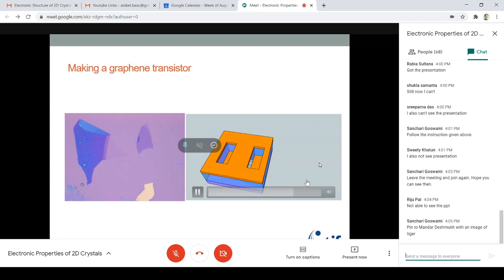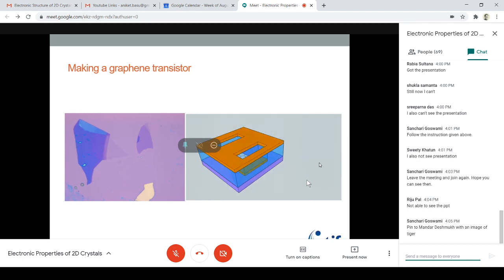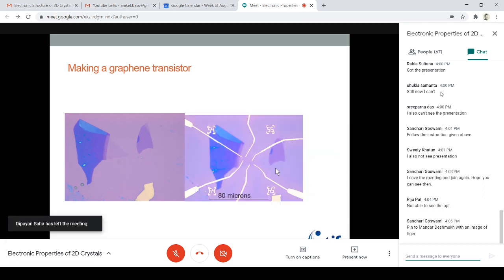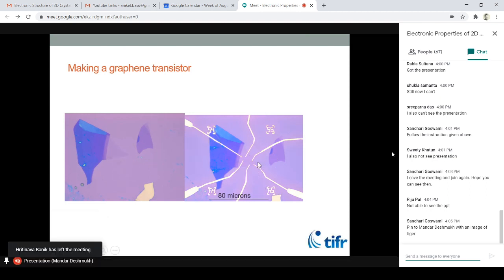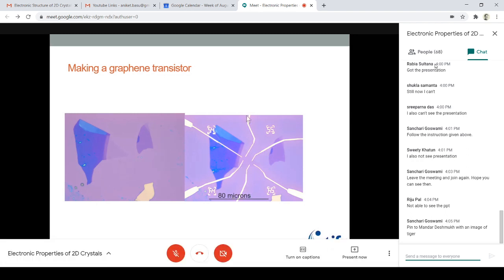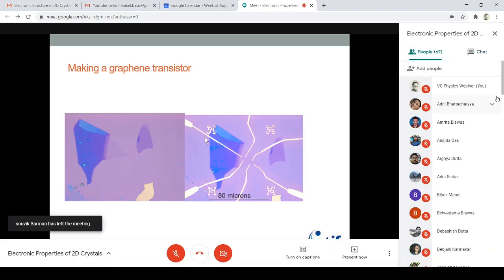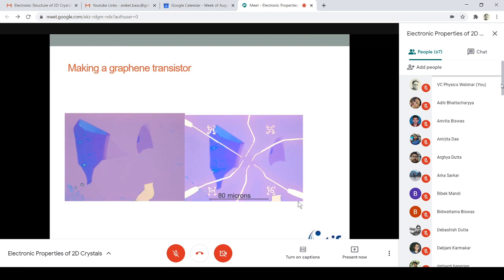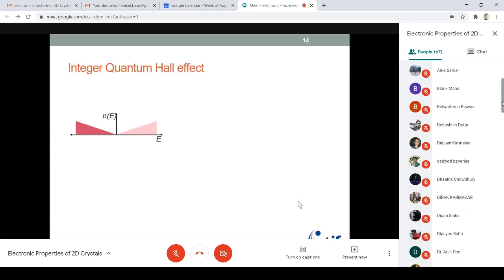So this idea is actually something very straightforward. If you have used a stencil to do anything in your school career, this is a way of making a stencil but using polymers. What you've seen is the basics of lithography, which is a complex process by which all the integrated circuits are made. And so at the end, once we put the electrical connections on it, by the process that I just told you, you have an electrical device where I can now apply voltage and measure current. Okay. So that's really the essence of the kind of measurements that one can do.